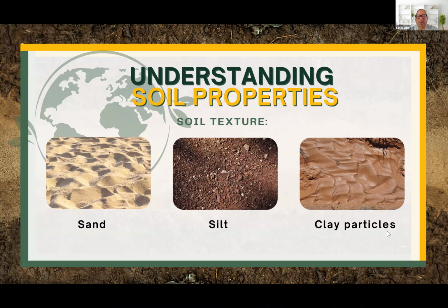The property of the clay soil is expansion and contraction. In other words, when it gets wet, let's say it rains, the clay expands and gets bigger. Then let's say it dries out, it's a sunny day, it's summer, and all of a sudden there's no water, and now you have all these cracks, like dry riverbed type cracks. So if your house is built on this type of material, you're going to have foundation issues. That's why this is one of the worst conditions to build on.